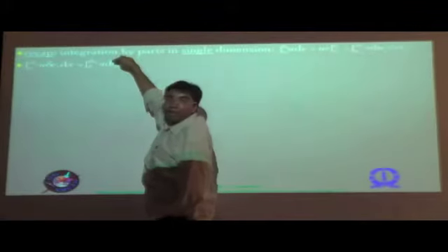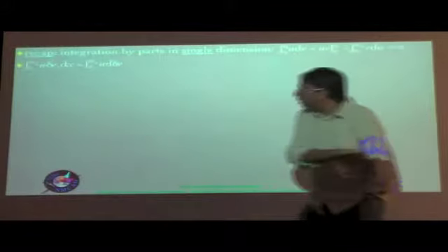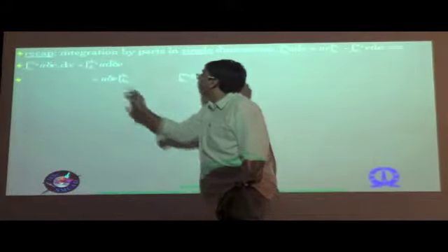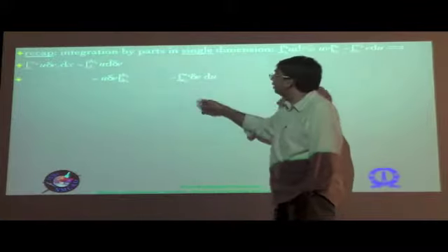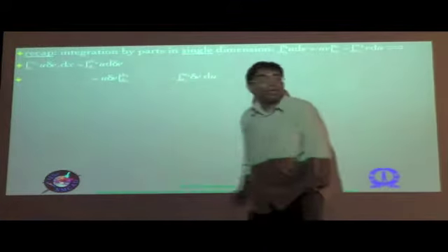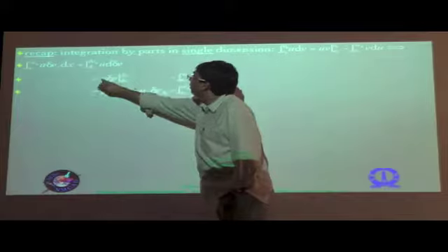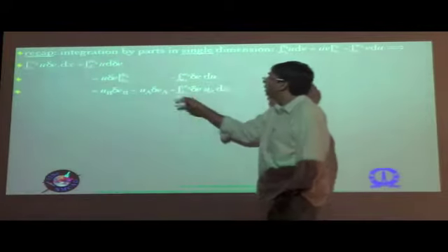So now we can think of this as an integral of u times dv, but instead of v you just have delta v. So we can use the same expression in order to determine that. So you see that this is u times v, instead of v you have delta v, and again v du becomes delta v du over here, okay, with of course the appropriate limits. So now that can be expanded out. So this both at the point B, so ub delta vb minus ua delta va.